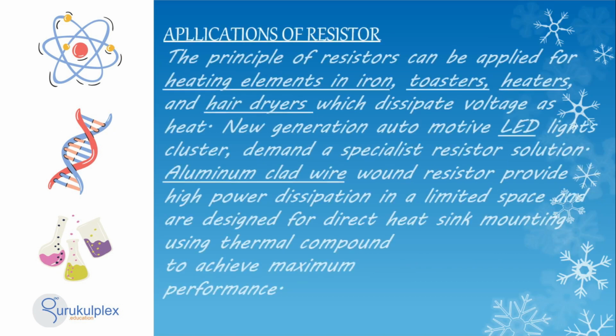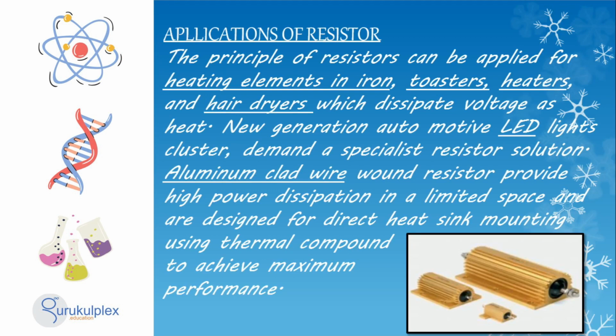Resistors have numerous uses in our daily lives, ranging from heating elements in irons, toasters, heaters, and hairdryers that transform voltage into heat, to automotive LED light clusters that necessitate specific resistor solutions. Resistors are critical. Aluminum-clad wire-wound resistors offer high power dissipation in cramped spaces and can be directly heat-sink mounted with the aid of a thermal compound for optimal performance.